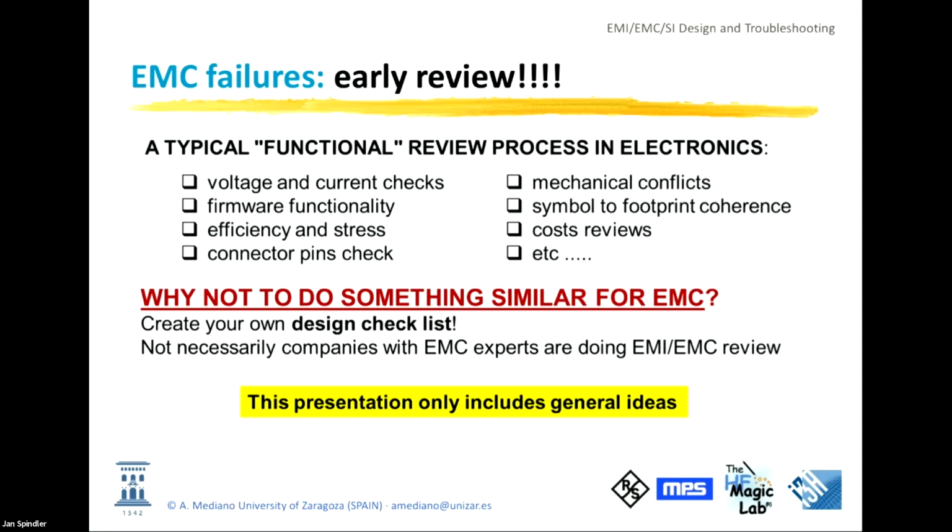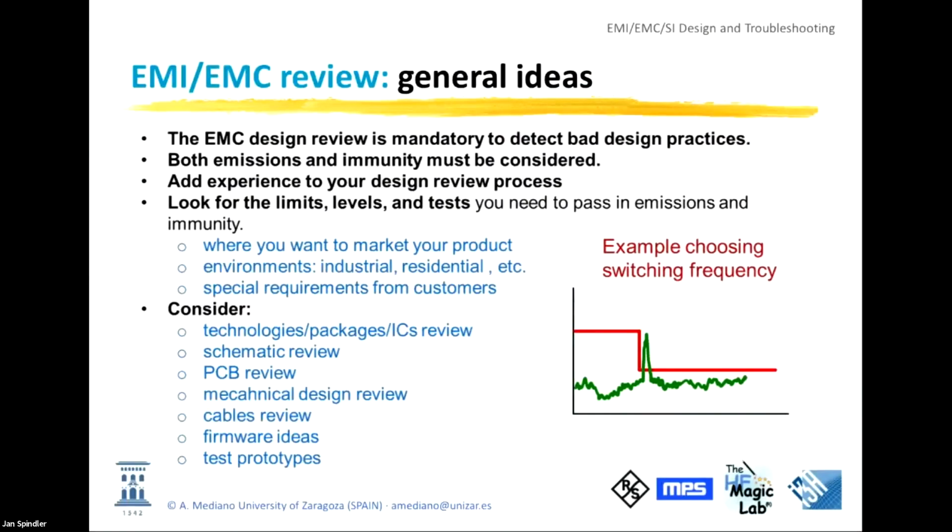And additionally, remember, just because you have an EMC department or an EMC expert does not mean you are doing EMC review. Many companies have EMC people working on solving problems, not reviewing the new designs that will go to production. So what can you do? Of course, this is not a full list because we don't have time, but let's review things that you obviously know. For example, remember to review emissions and immunity, both of them, not only emissions.